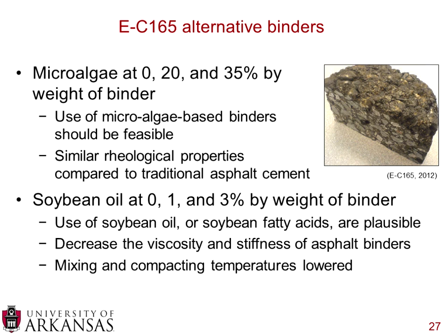So the first material that was looked at, and you can see a nice picture of the mix over on the right, is microalgae. They put it in at 0, 20, and 35% by weight of the binder. What they did is they took the microalgae oil and blended it with the asphalt cement at those levels. And their conclusions, very broad, very preliminary work, was that the use of microalgae-based binders should be feasible, and